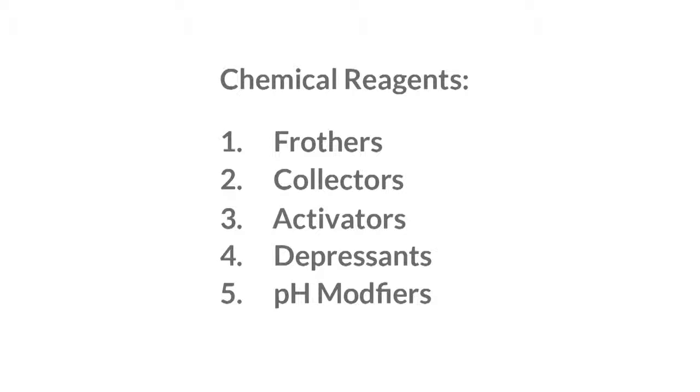Coal is somewhat naturally hydrophobic, and so it can be readily floated. However, most mineral ores are naturally hydrophilic. What makes flotation such a powerful tool for mineral processing is that we have learned how to selectively modify the surface properties of different ore minerals to make them hydrophobic. We use various types of chemicals, remembering that we've already spoken about frothers, but there are also collectors, activators, and depressants to control the particle surface properties.